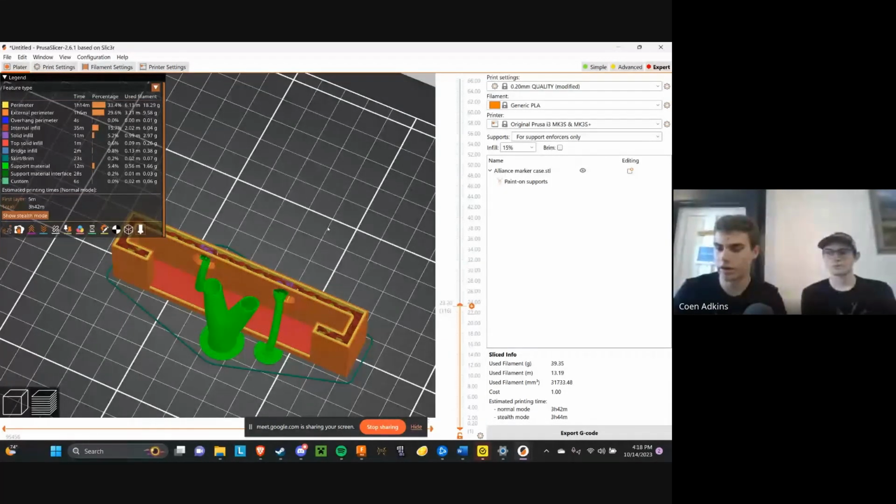They are either too bulky for us or add excessive weight where we don't need it. And so the 3D printing allows for a much more custom and smaller piece because you don't have to design around this separate mount. You just put a hole for the servo, make sure the screw holes line up. That way there's no excess material going around something where you're just going around that specific servo. And then that's the same with CNC parts.